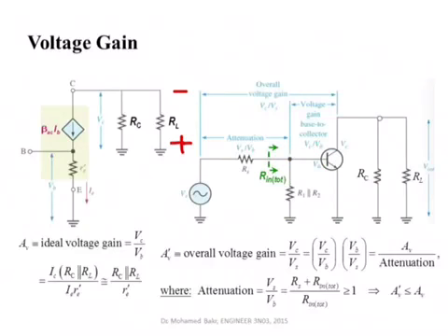So you have to multiply whatever answer you got by this attenuation. Actually, it's a voltage divider, so it's Rn total over Rn total plus Rs. Here they put it not in the form of multiplication but of a division, and then they use Rs plus Rn total in the numerator and Rn total in the denominator.